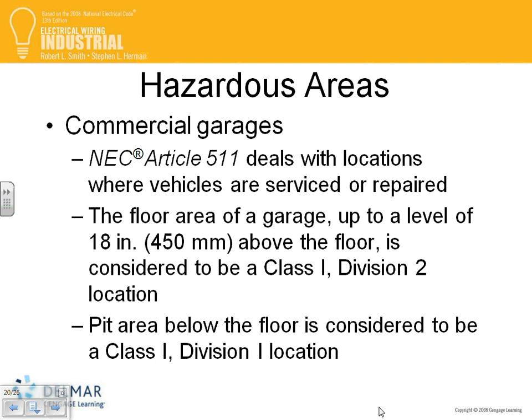Okay. Any question, guys, about the three classifications? Class 1, Class 2, Class 3, 501, 502, 503, 500 talks about all the stuff that we did. This is really the bread and butter of it. For us designers, all we need to know is what equipment you can use where, and when. And to summarize it: using rigid or intermediate threaded conduit with explosion-proof equipment at a Class 1 Div 1 location is the worst of the worst, with a group rating.